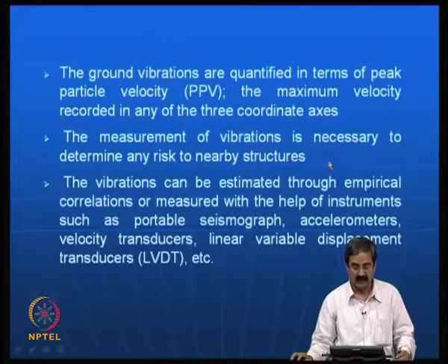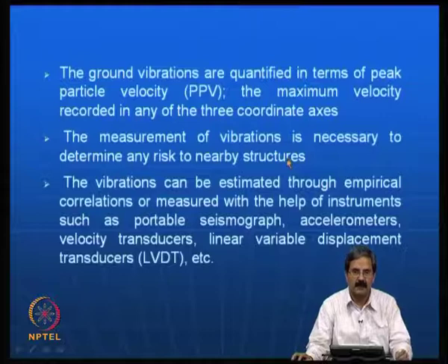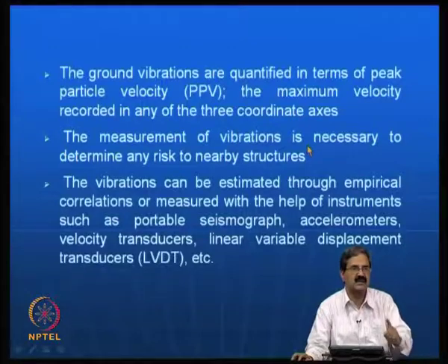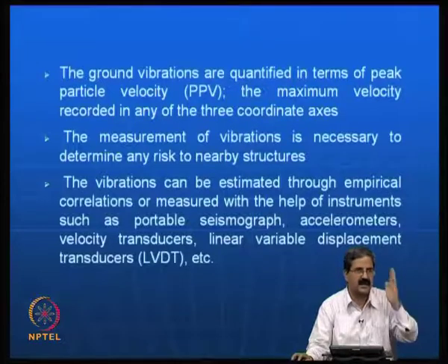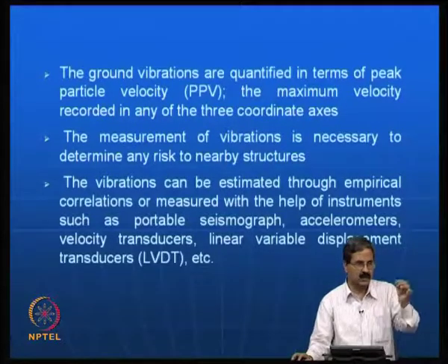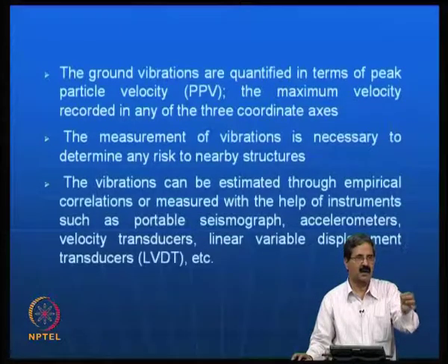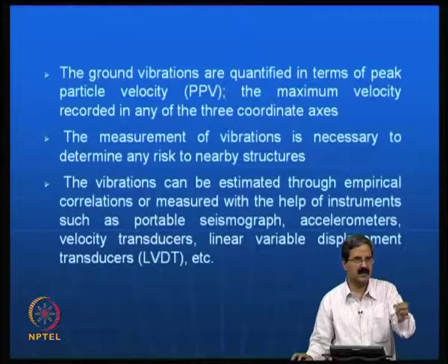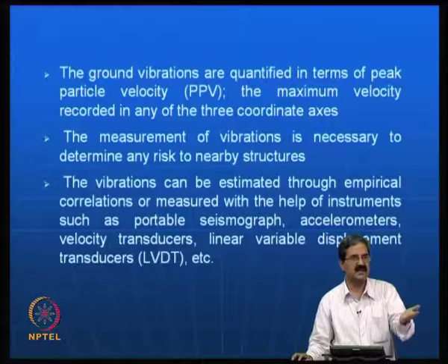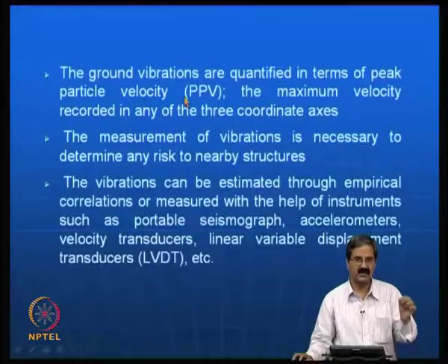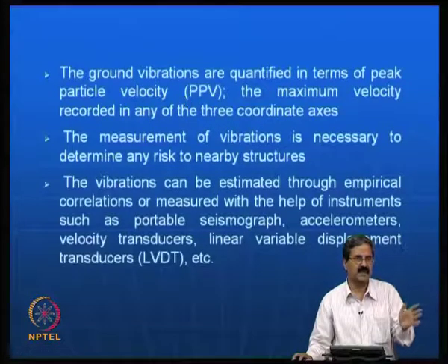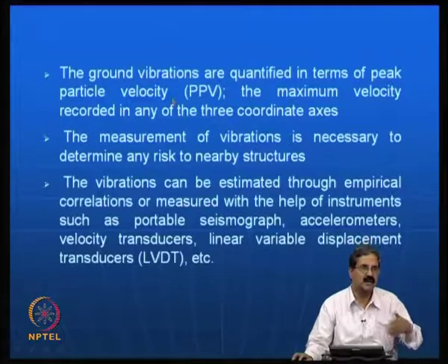So, this is one of the important ways in which one can measure the vibrations, and without vibration measurements it is very risky. There are a lot of cases where, because of the traffic, I have a lot of problems. So, you have to measure the vibrations before taking it up. Even if you are trying to construct a road or a big project, first take the velocity measurements, then construct it. If the peak particle velocity you measure is within acceptable limits, then you can say that my structure did not cause any difficulty to you.